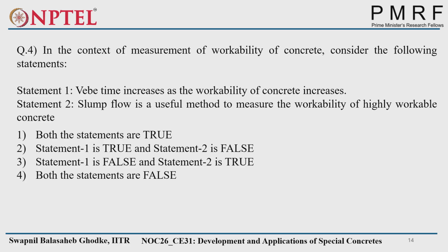So the next question is, in the context of measurement of workability of concrete, consider the following statements. VB time increases as the workability of concrete increases. And slump flow is a useful method to measure the workability of highly flowable or highly workable concrete. Which statements are true or false?